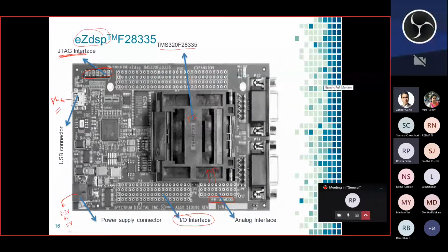In this, again, it is categorized like P4, P7, P8. So these are the categories of your GPIO pins. It is also important to know which pins we should use out of P4, P7 and P8, because arbitrarily you can't use any pin. It should be dedicated for some particular operation. And here you have P10, and these pins are for future expansion purposes. So they are not configured to any IOs, but P4, P7, P8 are configured for specific purposes.